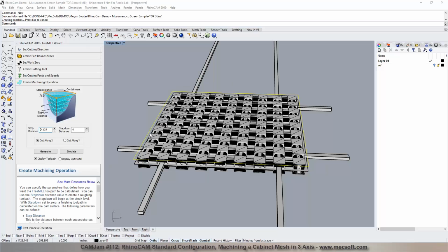Whereas this one, yeah, we've created the rough. It goes to the whole entire length of your part. So you need to clip these and make sure it's in the area that you want. So you don't really have any containment in the free mill. That's where you've got to be careful. You've got to be exactly where your geometry stops, and your stock has to be exactly centered to make sure it doesn't cut all the way through your stock. So it's a little more cumbersome, a lot more cumbersome, I should say. And so this is mill.